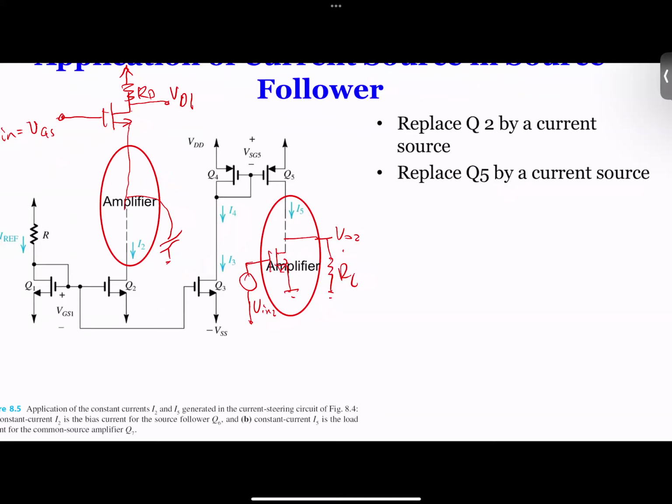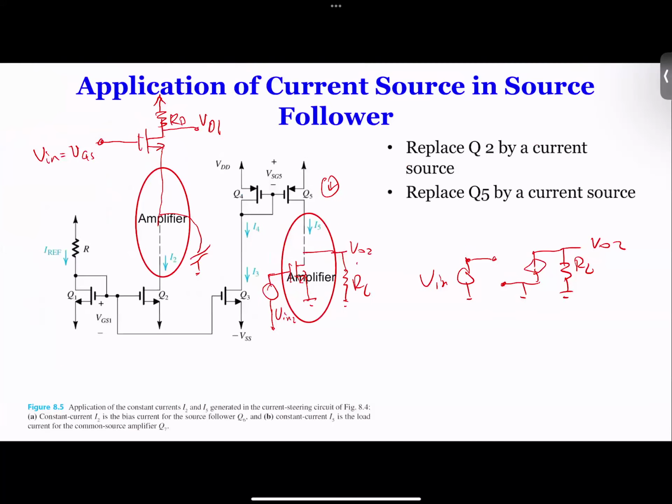So the whole circuit over here will become, because this current source over here, that whole thing, the equivalent current source, is gone in DC. It's an open circuit. So all the way, I5 is open. Therefore, only one resistance can connect to output. So this is a very basic gain unit. We're going to take a look at this also later on.